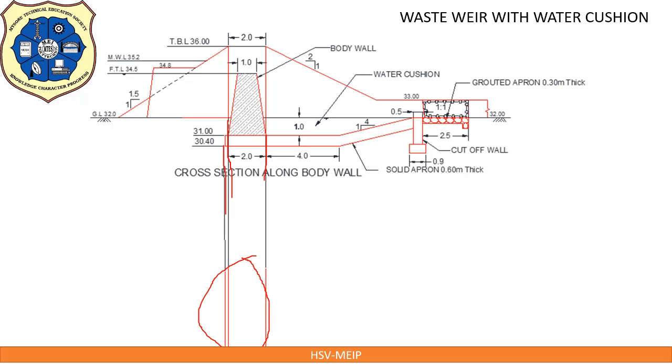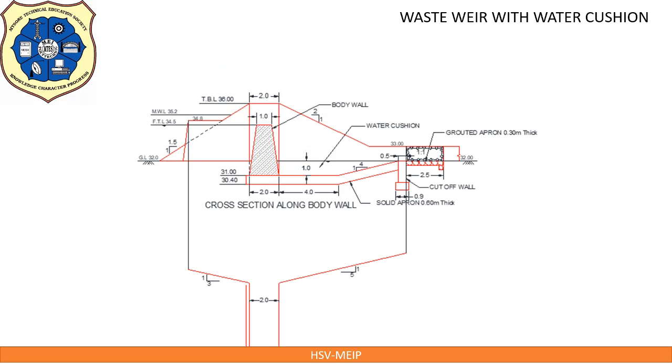At foundation level, because we are drawing half plane at bottom. Draw a splayed portion of upstream wing wall and downstream wing wall, that is 3 horizontal to 1 vertical on upstream side and 5 horizontal to 1 vertical on downstream side, given in the problem. Wing wall should be extended up to these 2 points.